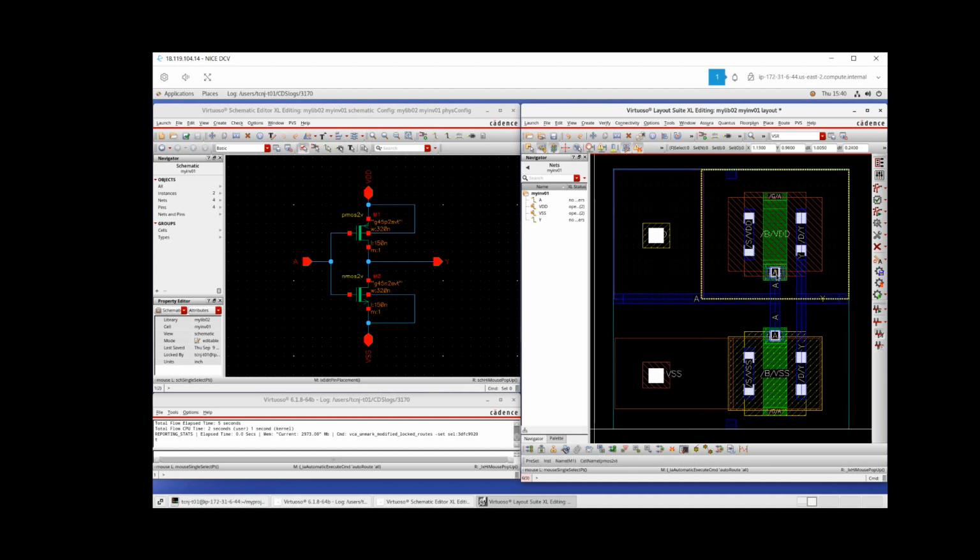Well, we're going to leave it for now, but one thing that you could have done is to stretch the poly, so basically you're connecting both gates with poly, and that's okay. This is a very short distance, and then just have a single metal connection to the poly with a contact to poly here. But we're just going to leave it like that.